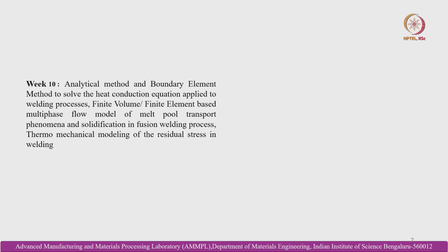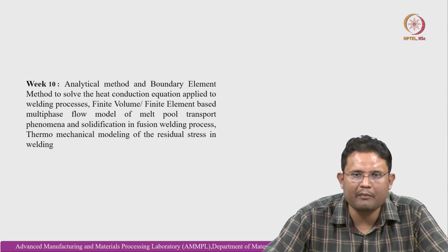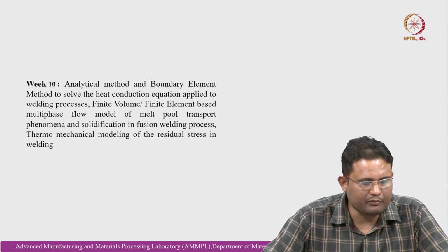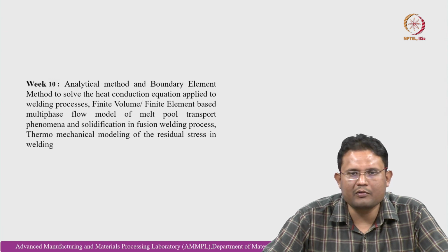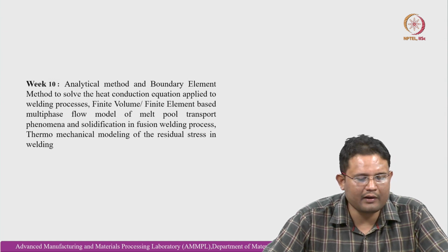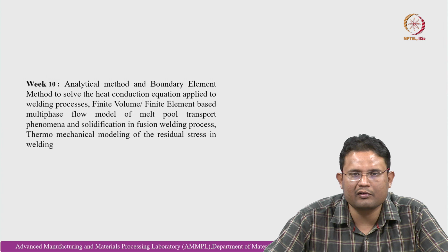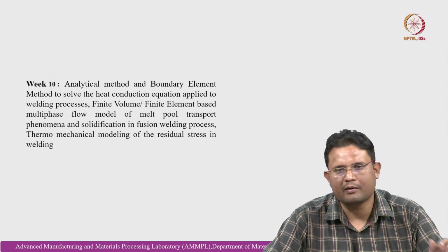These are the contents: the analytical method and boundary element method to solve the heat conduction equation applied to welding processes, a finite volume based multi-phase flow model of melt pool transport phenomena and solidification during fusion welding, and also thermomechanical modeling of the residual stress evolution during welding processes.